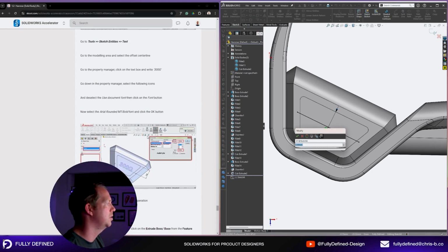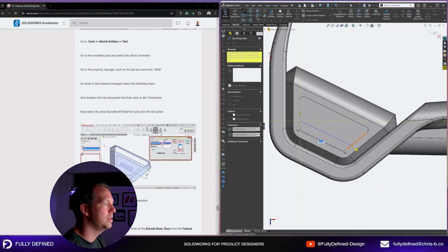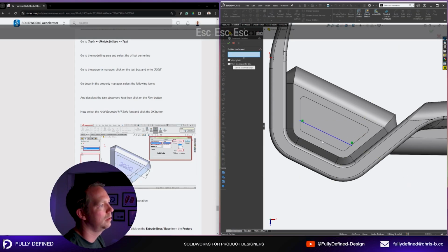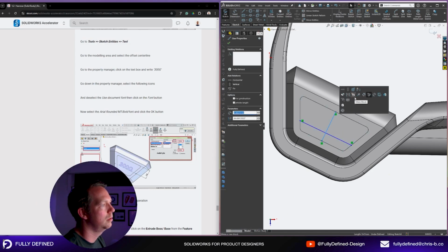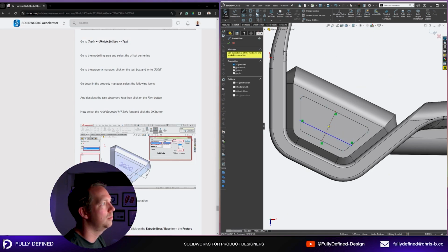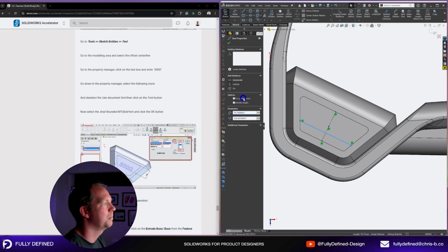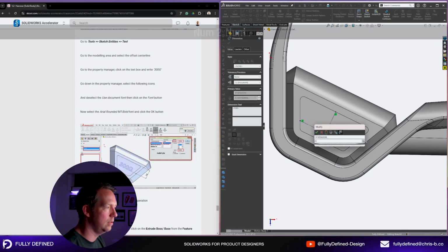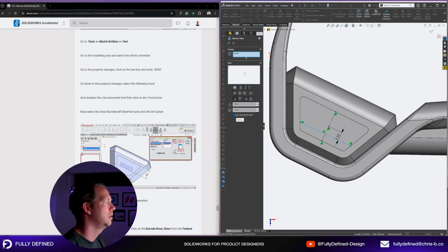Cool. All right. So here's a trick with some text. I'm not going to offset. Let's say I want my text to be 5 millimeters high. I'm going to set up a line that goes right through the middle. I'm going to just find a midpoint. I'm going to have another line that's going the opposite direction. In fact, they're going to be perpendicular. I'm going to make sure the dimension between the center point and here is 2.5. And then I select this line and do my text.